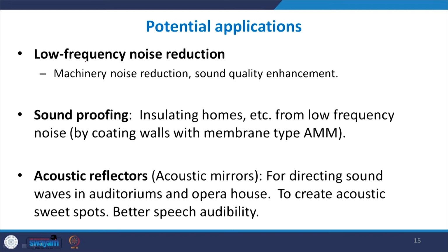Here low frequency noise reduction is mainly common in machinery noise reduction. Machinery noises are low frequency, coarse sounds, whereas human speech, whistles, etc., are high frequency. So usually low frequency noise reduction is done to curb these sounds and make speech or communication better, so as to reduce the speech interference level.